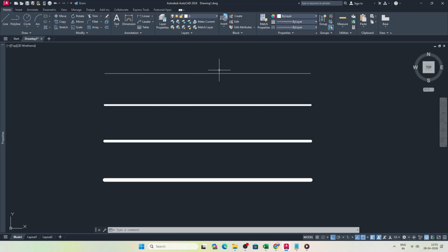With LWDISPLAY turned on, the line weight icon accessible, and your objects inheriting settings properly, you should see the line thickness you intended right there on screen.